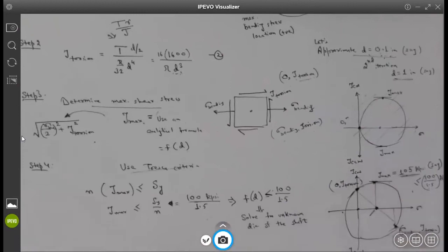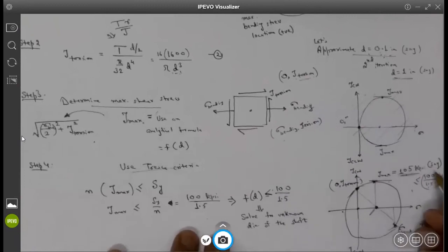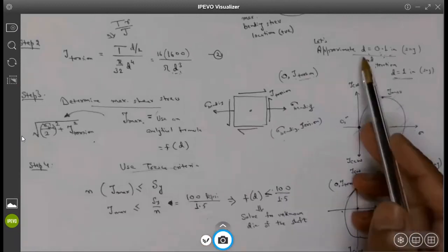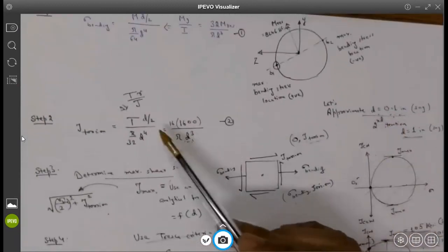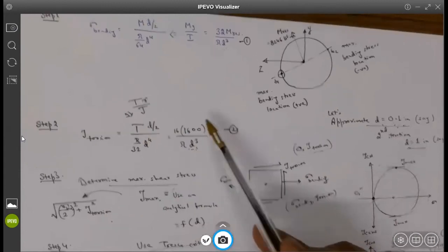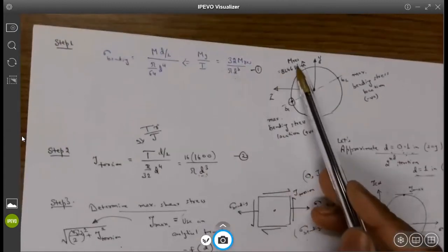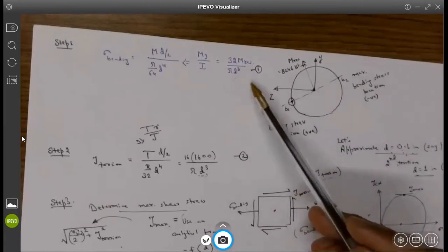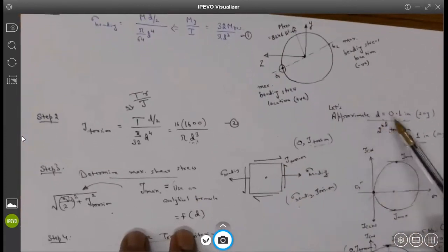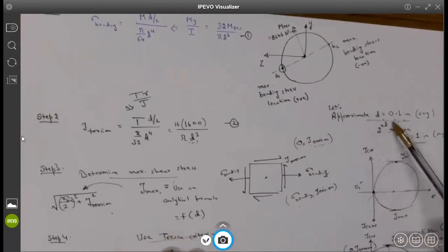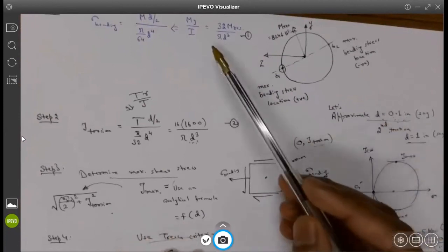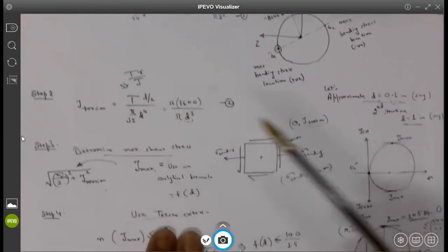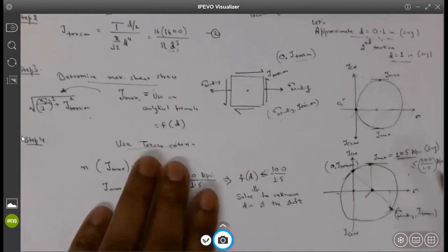Yes. So that is how I actually, and I said "say" because I don't know what that number is going to give me. I know what my T is, which is 600 pound force inch. I know my M resultant, which is 8246, but thereafter, since it was taking too long, I just left the calculations. I didn't ask you to do the calculation. You can do it yourself and say if D is 0.1 inches, what these numbers are, and what my tau max is going to be.